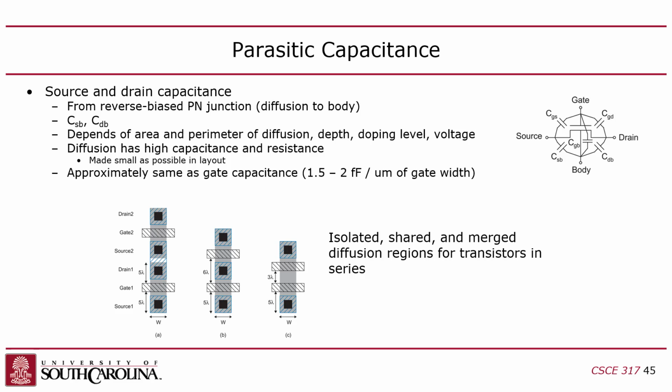So, first of all, how do you make wider transistors? There's a couple of ways to do it, a couple of tricks. This will be a little bit confusing because I haven't shown many top-down pictures. I've shown the cutaway pictures. But when you design a chip for manufacturing, the design looks like this because you're looking from the top down, right? And what you're seeing are these polygons, and each polygon represents a layer.